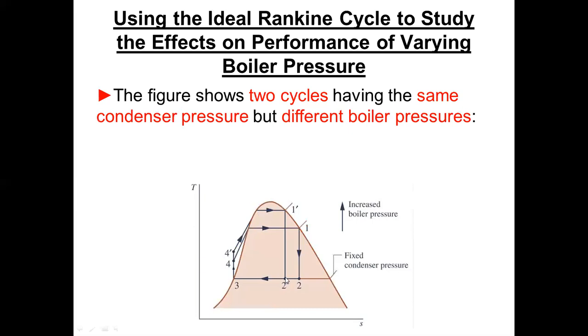This is for an ideal cycle. And then we reject heat at the same temperature. So the average temperature of the heat rejection has remained the same. The temperature of the heat addition has increased. So this will definitely increase our boiler efficiency, but the turbine's going to squawk because it's going to incur more damage. All right. So now I'm catching up with the slides.